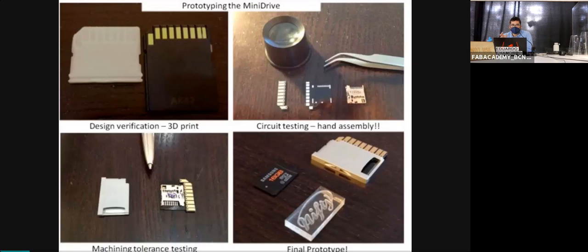And this is where we are reaching the big three, which is 3D printing, laser cut, and CNC. They are the big three technologies of digital fabrication. And you never use just one of them. You combine them when you prototype. You use each technique for what it does best. CNC usually is slightly slower and takes more time to set up the values and parameters to get a good cut. But on the other hand, you are getting a really good and accurate cut, and you can cut really expensive materials.